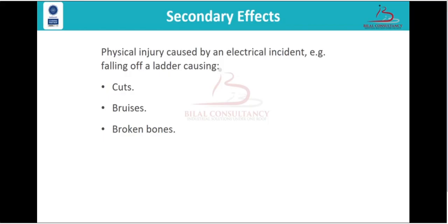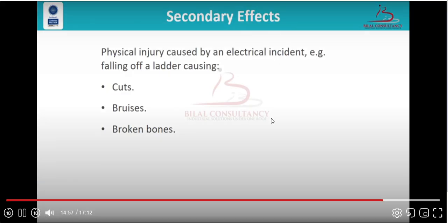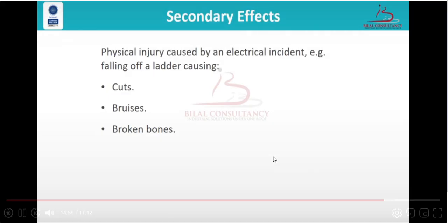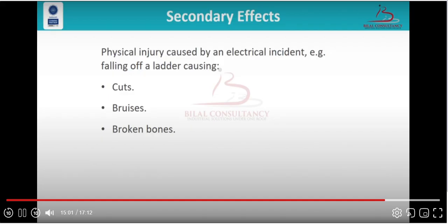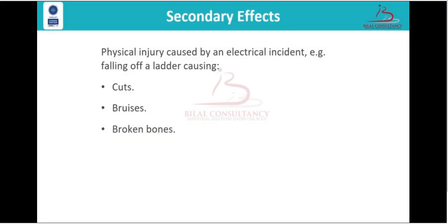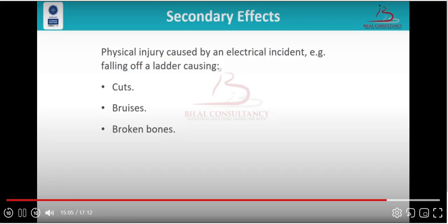Repairs carried out by unauthorized personnel or carried out badly, for example, split flex taped up with insulating tape. Continued use of faulty or defective equipment. Chemical damage to the flex, for example by corrosive wet cement. And in the end, lack of routine inspection, testing or maintenance. Moving forward towards the use of electrical equipment in wet environments. Because water decreases the resistance of objects and environment.